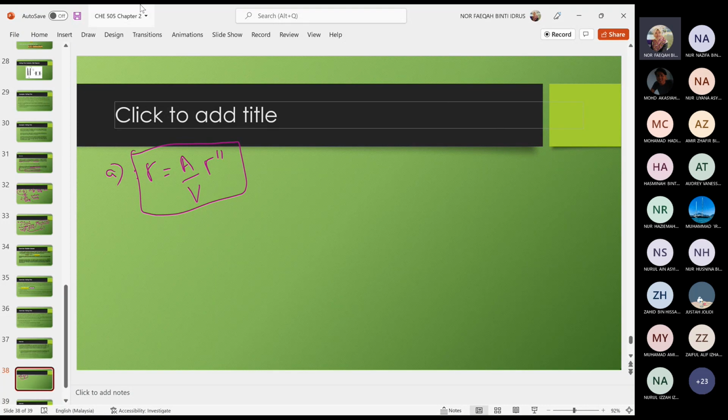Okay. So, R equals K CA CB, and it's equal to A over V. This R is the pseudo-homogeneous one, K CA CB, and it's also equal to A over V multiplied by the rate of mass transfer, which is KMA, times CA in the bulk fluid minus CAB, over 1 plus K prime over KMA. The bulk fluid should be B, to distinguish from the product B earlier. So, where does this equation come from?